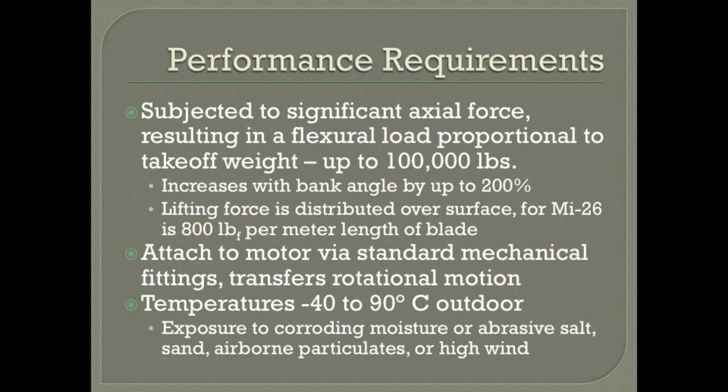Additionally, to generate forward or aft thrust, the vessel must bank, and this further reduces the aerofoil area to generate lift, increasing the amount of force required on those particularly exposed areas. Additionally, as weight is a critical factor in aircraft, this converts the modulus to a specific modulus. Also, as the blades are exposed to the elements, they must be able to resist water and wind and sand erosion due to their operating conditions, when they're in a wide range of temperatures as well.